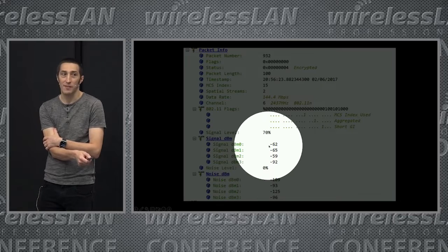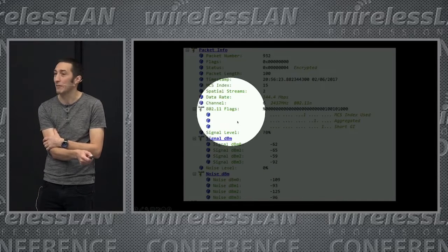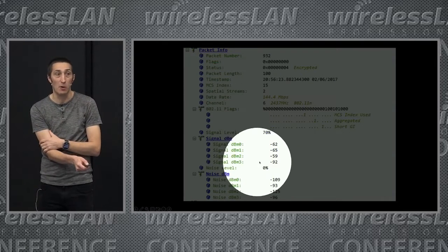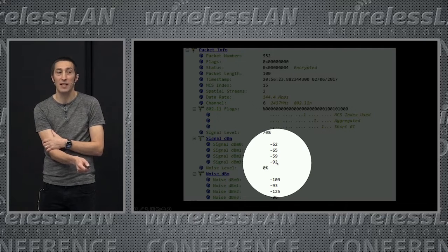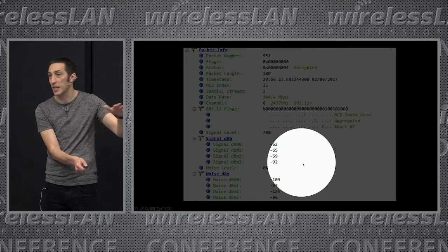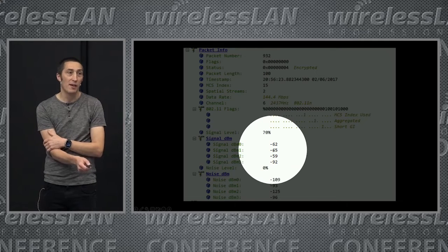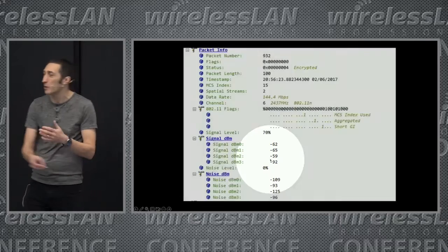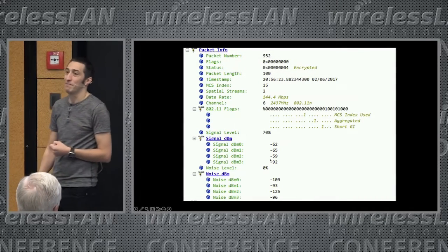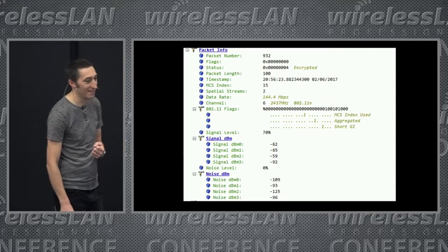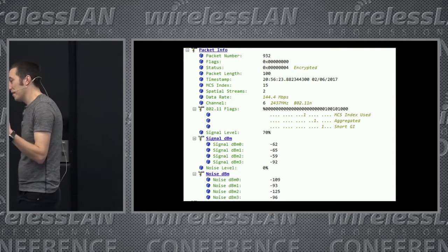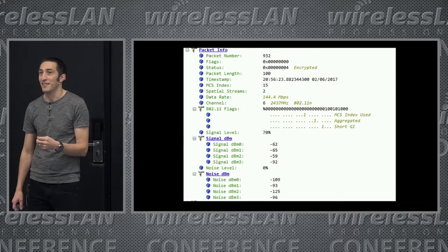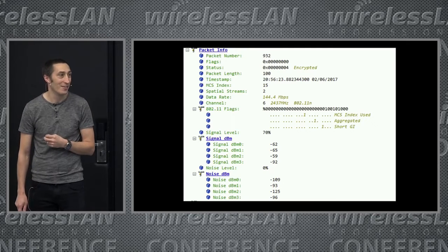Well, that's exactly what these drivers do. They then give an overall signal level, some sort of magic in the driver to come out with a signal reading. But the raw signals, and look at them, one of them was minus 92. Now, I'm sure we probably didn't use that because that was one that wasn't very good, and the others are closer to each other, minus 62 to minus 59, but there's still some variation. So, I'm telling you all of this to help you realize that RSSI isn't a really accurate signal reading.